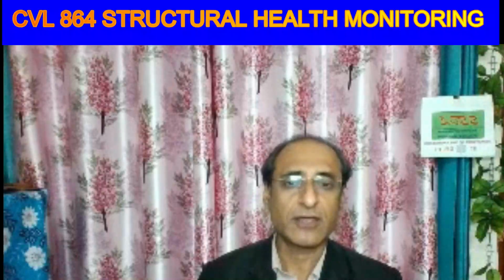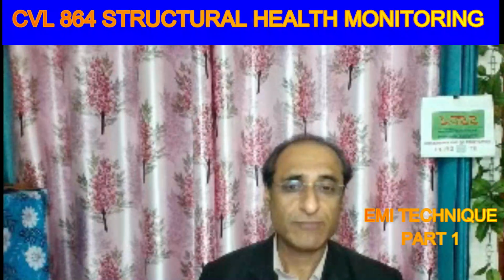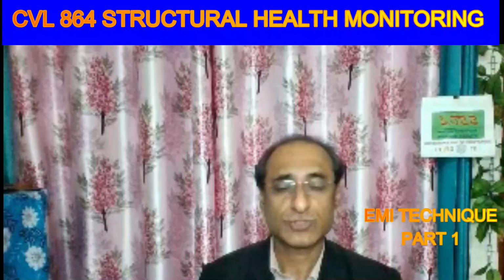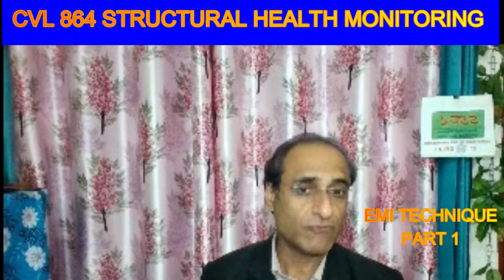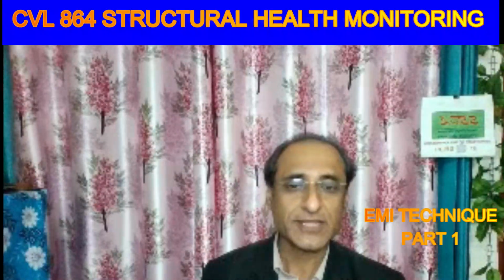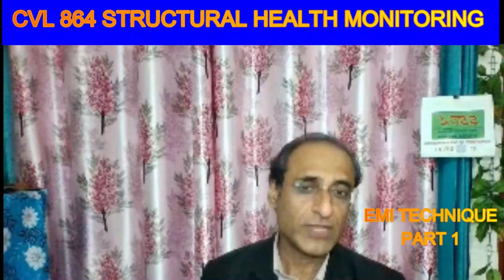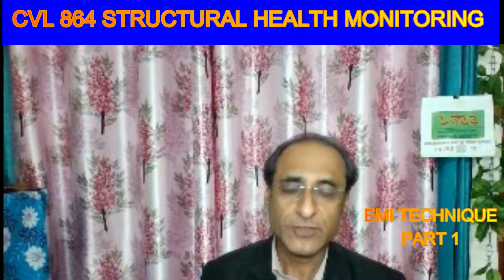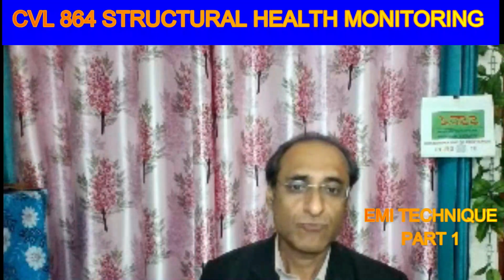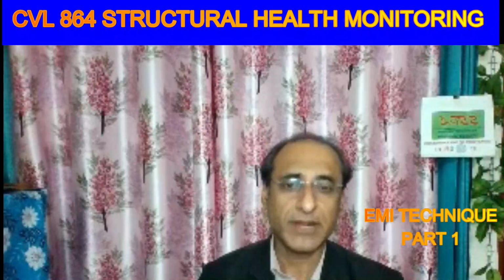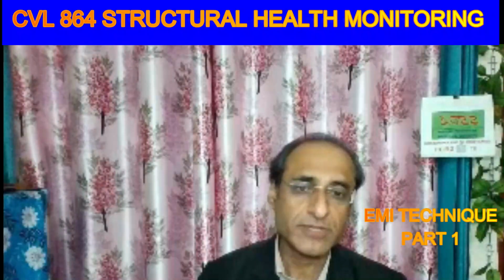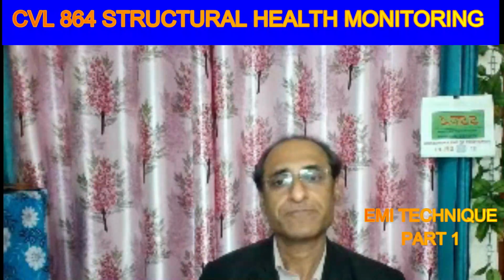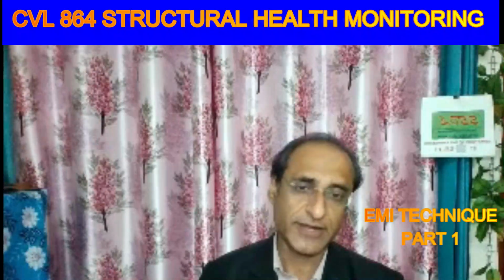Yes, this part we will be doing in the coming lecture. In this lecture, we have not focused on the computation part, we have focused on the measurement part only. We are showing you how the measurement is made, and we are measuring electrical admittance. So what we are obtaining is electrical admittance, and when we do root mean square deviation, we are doing it with the electrical quantity directly. But yes, your intuition is absolutely right. We can use the equation derived by Liang to obtain the mechanical impedance of the structure, called the drive point mechanical impedance. That computational procedure we will learn in the forthcoming lectures.